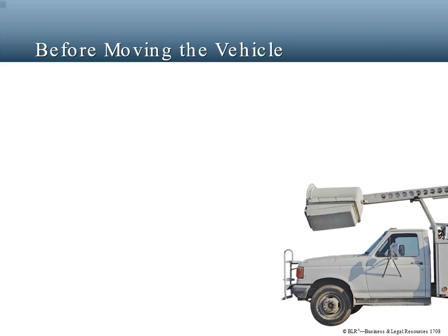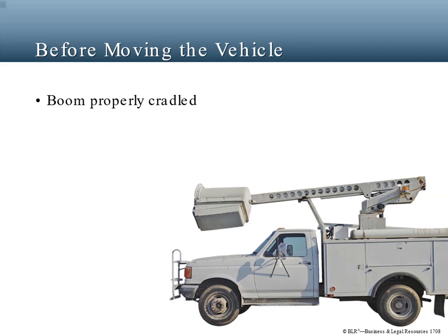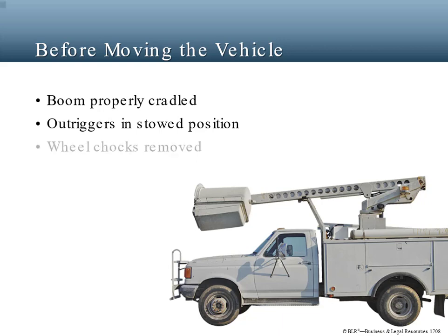After work is completed and before moving the vehicle, make sure the boom is properly cradled. Ensure that the outriggers or stabilizers are returned and stowed in position. Remove wheel chocks and ensure that the path of travel is firm, level, and free of obstructions, both on the ground and in the air.